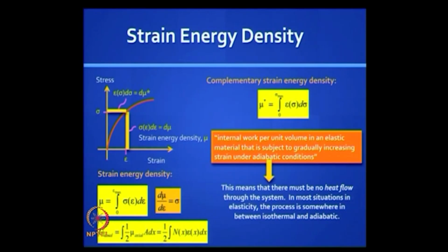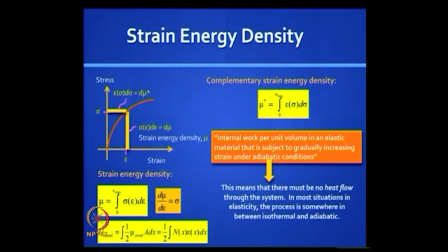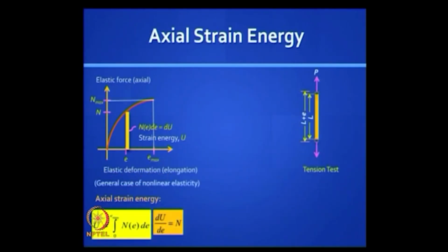Here you visualize the incrementing of energy coming from an increment in the force, or the stress rather than in the displacement. You know, you can do loading either displacement controlled or force controlled. So if you do it force controlled, then the product, which is also energy, would take this form, and we refer to it as u star, and it's the other complement of the rectangle which contains the total energy. Sometimes it has a physical meaning, often it does not.